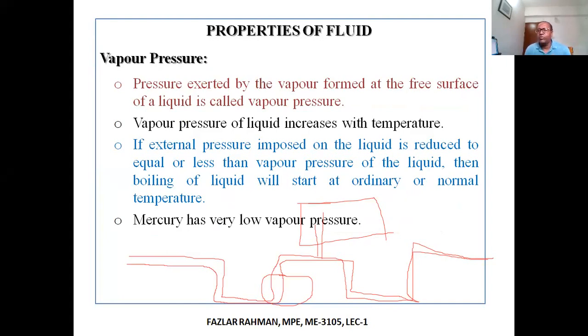Right now we boil water in our kitchen, our pressure is 14.7 psi. So at earth level, you boil water, all of the water will boil at the same temperature. But if you take it to the top of the hill, it might boil at 90 or 80 degrees, because the pressure at the top surface of the water is less.